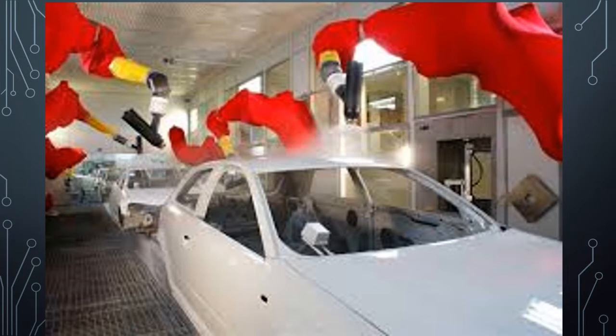Now, if we got down into maybe a more complex body panel where overlap is a much bigger deal, and it's much harder to go off the panel, then we might need a very controlled path. But for something like this, that's a big wide open area, point-to-point or continuous path would probably work just fine.